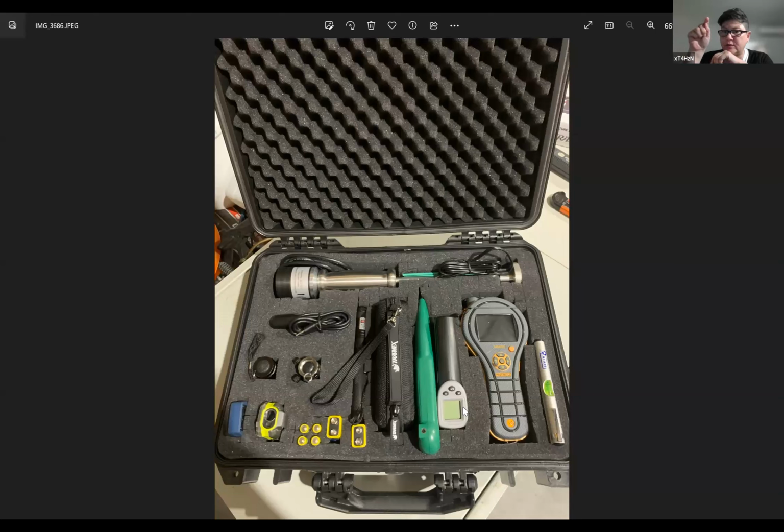That little dot that you see with the light is a laser. It's a laser surface meter. So when you take that, you point it into a ceiling, not only do you see the laser light, but it also looks at dew point on a ceiling, should there be any. And that is a very good indication of moisture within a material that's wet.